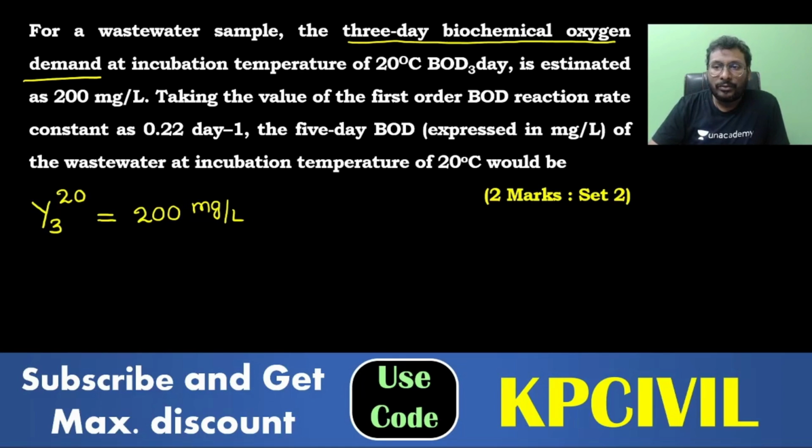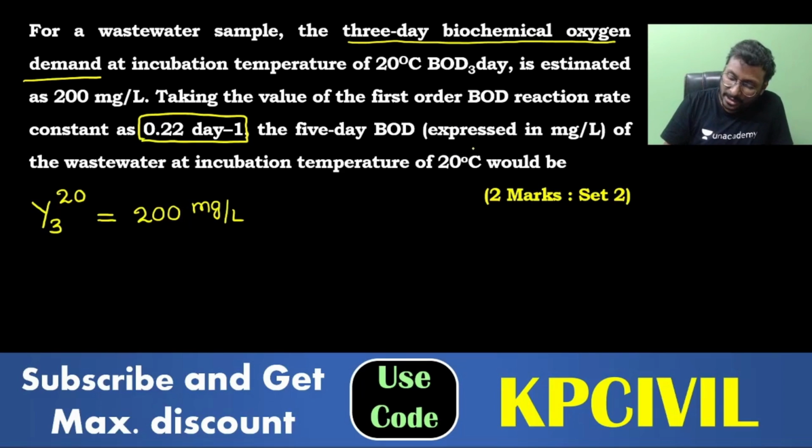Taking the value of first order BOD reaction rate K as 0.22 per day, what is the 5-day BOD of the wastewater at incubation temperature of 20 degrees Celsius, Y5 at 20?